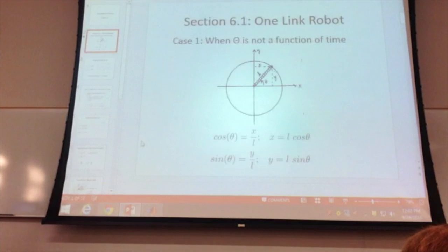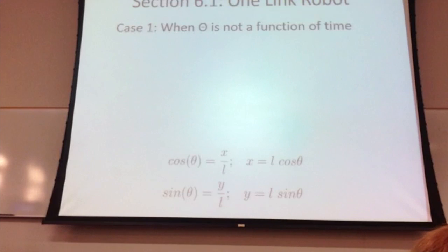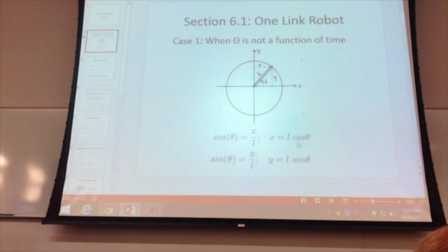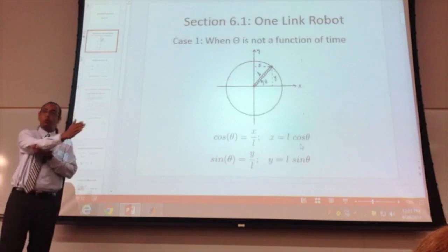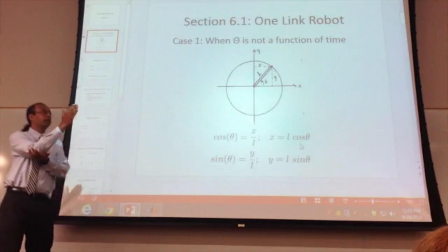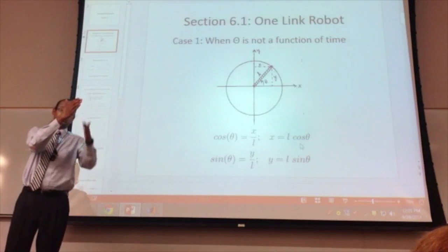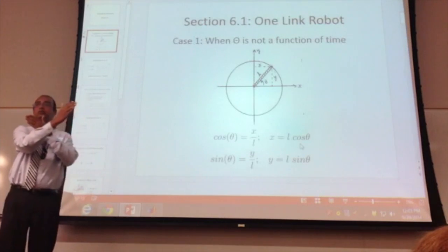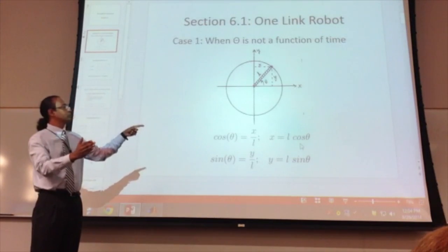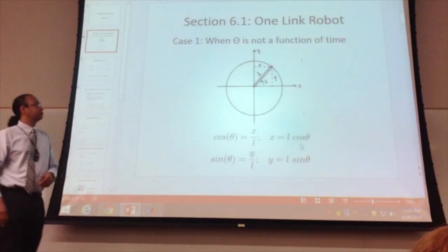test on this one. All right, so what we did last class was we continued with what we started the first time we met, when I taught you about the one-leg robot in the lab. If we have a one-link robot, we can position the link at different orientations, and we can plot for every orientation a projection on the horizontal axis and a projection on the vertical axis. That's given by x, which is L cosine theta, and the vertical is y, which is L sine theta.